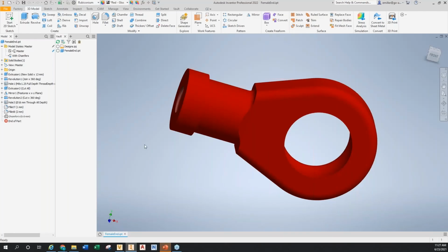All right, so this is just your regular Inventor interface here. I always like showing the Vault tab, so I like to put that right next to my model browser. I'm a right clicker, so basically you can right click on anything in your Vault browser, do your checkouts, check-ins, things like that, change the states. So if you're using Vault, definitely I would recommend, and this can be hit with the plus sign, add those tabs. And you can move those around, they're dockable. So if you don't like having so much space on the left, you can do that.